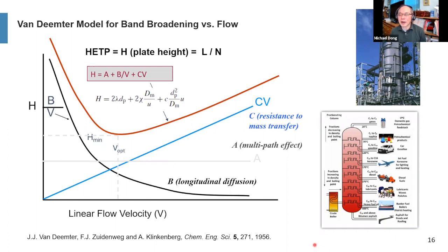Now here is a big column. It's called a column. They're at least 5 stories high, and they have different plates inside the column. These are bubble plates. You put crude oil in the bottom, you heat it up, and then at the outlet you have methane, which you burn. And you make naphthas, gasoline, at least 30% gasoline, kerosene, diesel, lubricant, heavy fuel oil, right? Number 2 heating oil, number 6 heating oil.